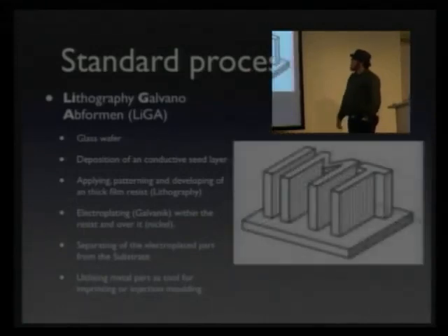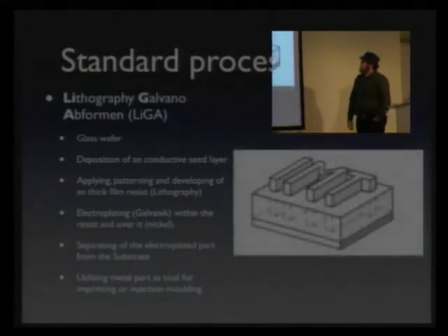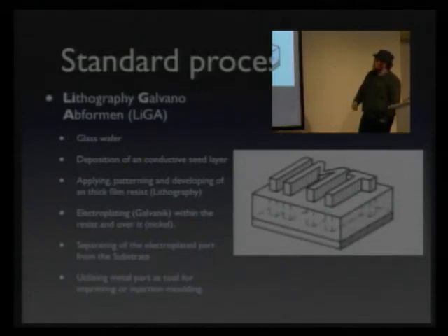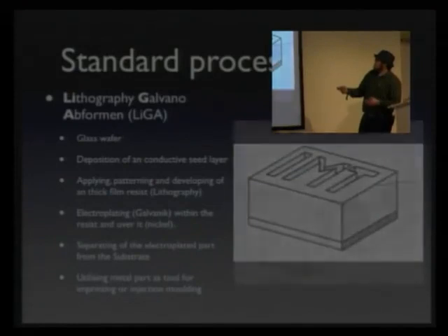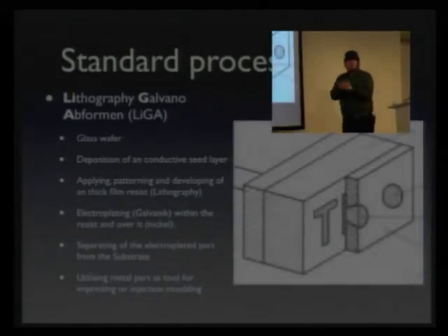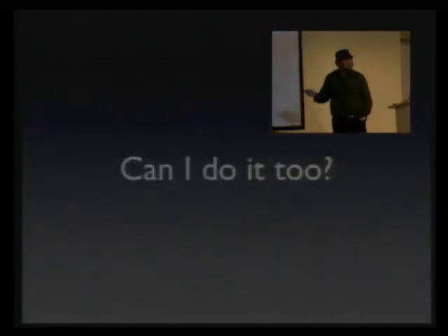Then you structurize it, start the electroplating process, and grow over the structure. Then you remove the whole thing from the structure and press the plastic into it to reproduce the structure you had originally, which is very cheap because you can do a lot of them quite quickly, and it's standard technology. You can put this in any workshop and they will do it.